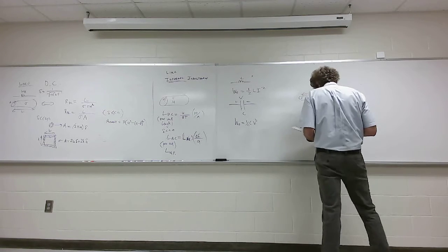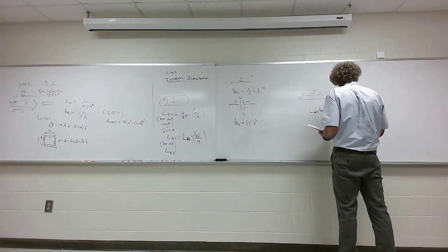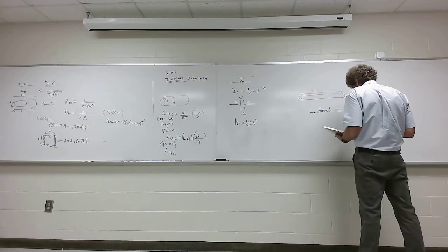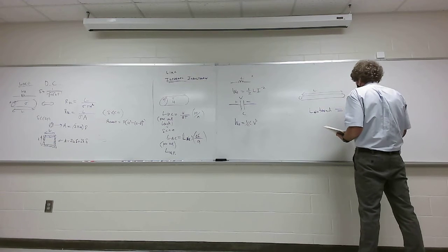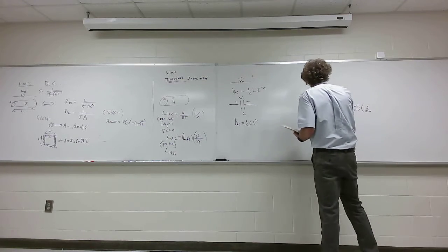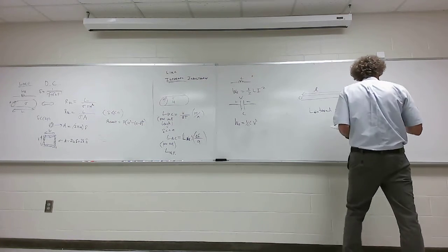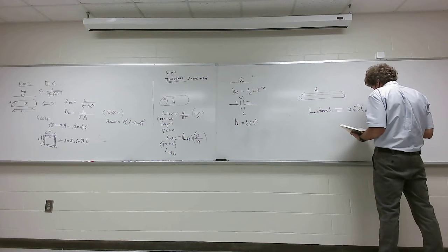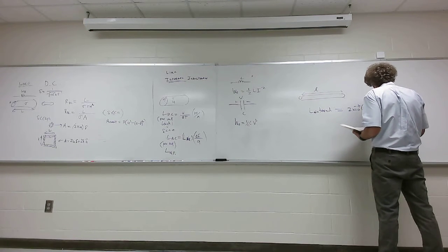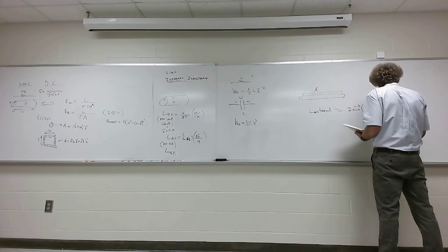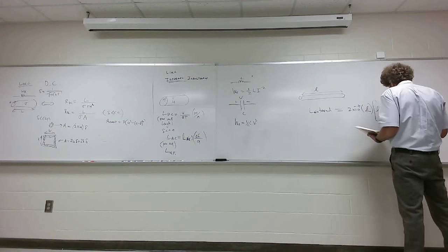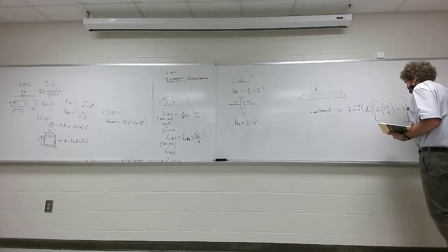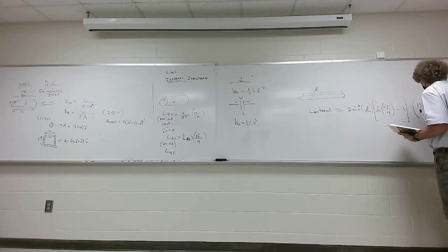And this isn't per unit length. It's 2 times 10 to the minus 7th henries per meter times the length L. And maybe I should use the script L he uses here, because L usually means inductance, times script L here. And then it's times the natural log, or log base e, of 2L over A, minus 1. And this is in henries per meter.